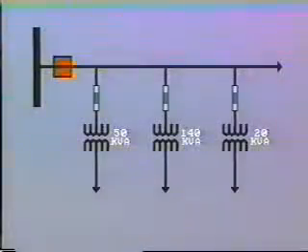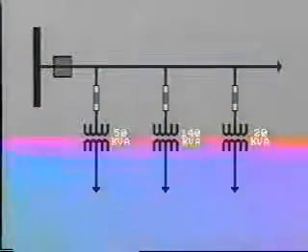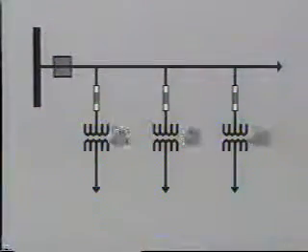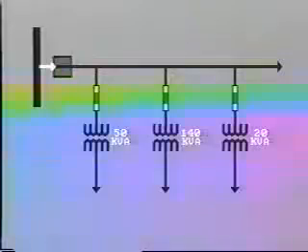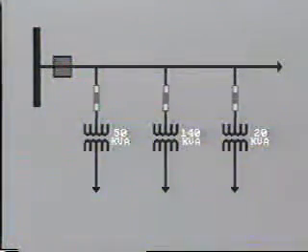On smaller transformers, it is usual to omit the primary side breaker for economic reasons. Typically, we may have many large and small distribution transformers tapping off a distribution feeder. The feeder will be fed from the substation bus through a breaker, but each distribution transformer will be protected by high-voltage fuses only.